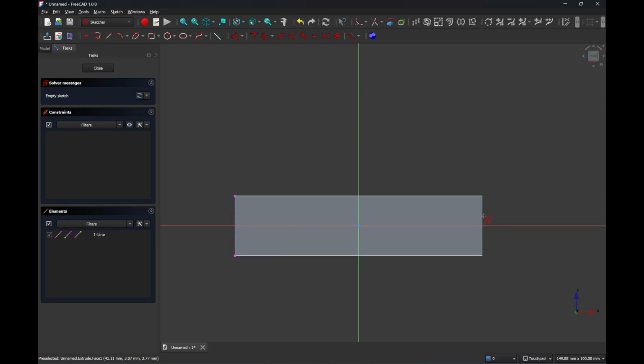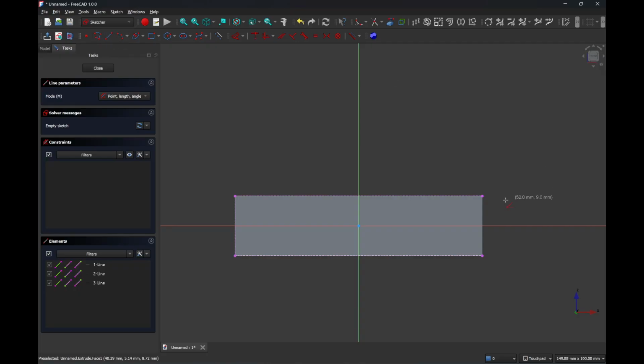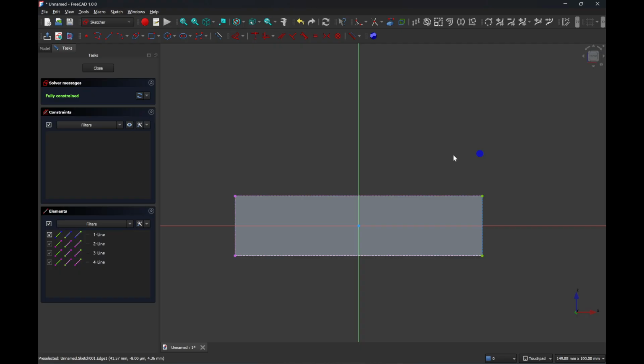There is no right edge because when you do the extrude, it sort of starts at this end, comes around, but what it does have is the top and the bottom. So we'll create, for our purposes, a little bit of geometry. So we can choose, so we'll create some construction geometry. So we've selected the top, the bottom and the left, and we've created some construction geometry on the right.